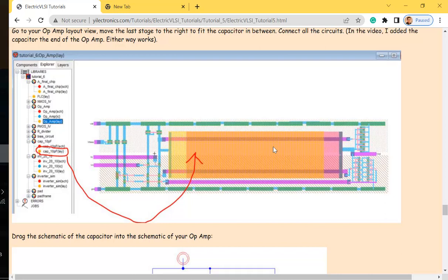But for power electronics, like all these power grids, probably 1 microfarad is not that big. But for whatever we are dealing with on the bench, 1 microfarad is a big capacitor. For integrated circuit design, whatever is being fabricated into the chip, like all these ICs, they are at the picofarad level, like 20 pico, 100 pico. So 1 micro is actually a big capacitor.